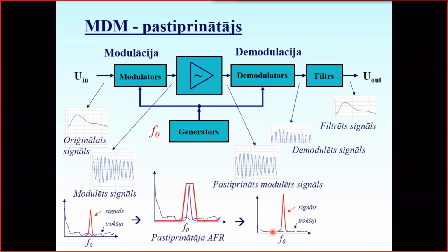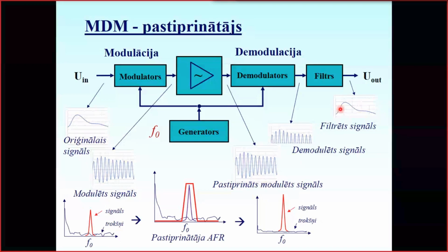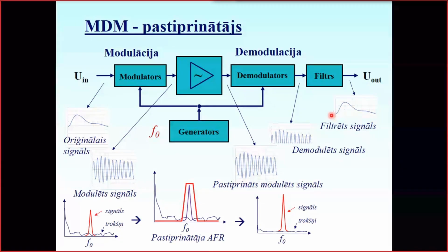And then we put it into a demodulator, for instance, the same peak detector, and we get the waves of the amplitude. So we get the filtered signal: we demodulate it and we filter it. We use a peak detector or envelope detector, what we just discussed, and we get the output signal, which has a higher amplitude because the original modulated amplified signal has a higher amplitude, and we actually have reduced noise. So this is one of the principles.